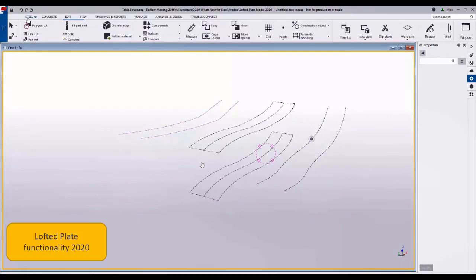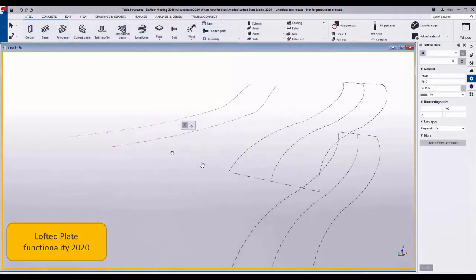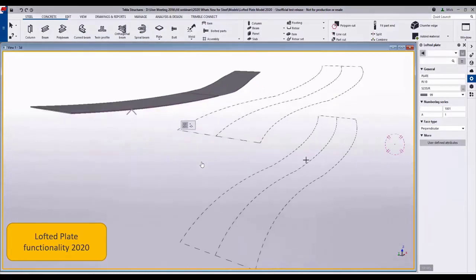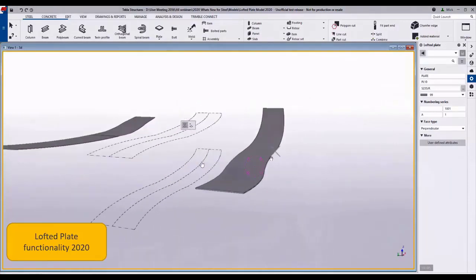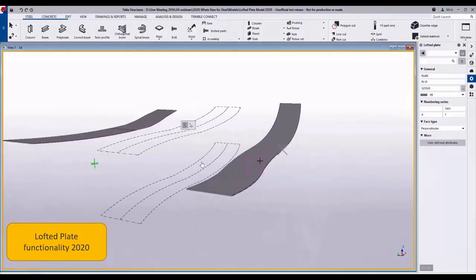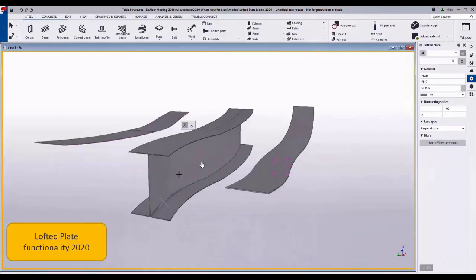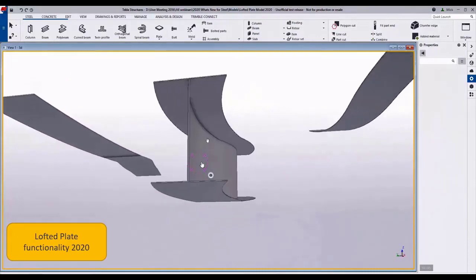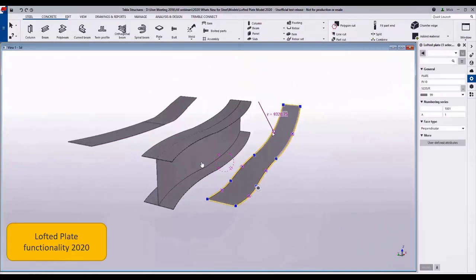Once you define those, we can then say, okay, let's create a lofted plate between the polycurve drawing objects. And you can see the lines I just introduced there. If I select those, I've created that really complicated, twisted, swept, lofted plate element. For the built-up beam, top flange, bottom flange items, web plate, defined by polycurves as well. So nice simple way to create these really complex items.